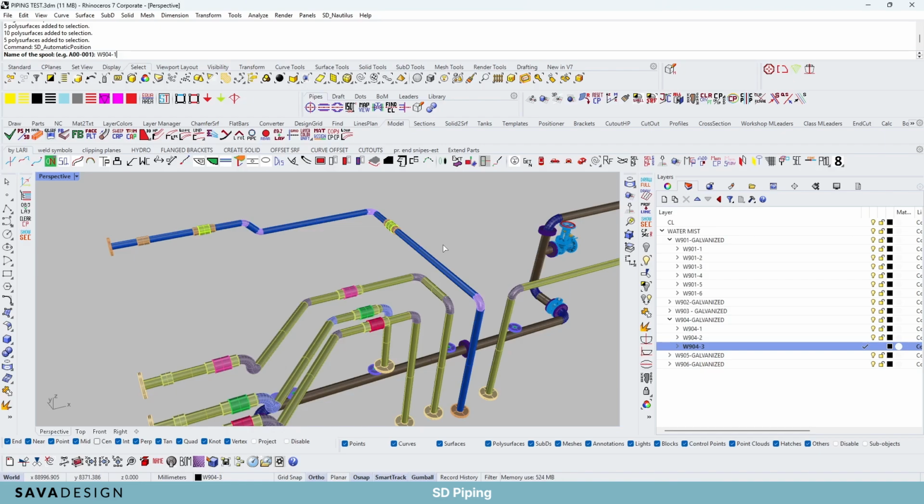I make the line, then I create a pipe. I add the connection, the flange. Can I split the spool after I made the pipe and add some flange, for example? Yes, that is not a problem. You only have to pay attention to how you split things. So that will only come down to your organization of the layers.